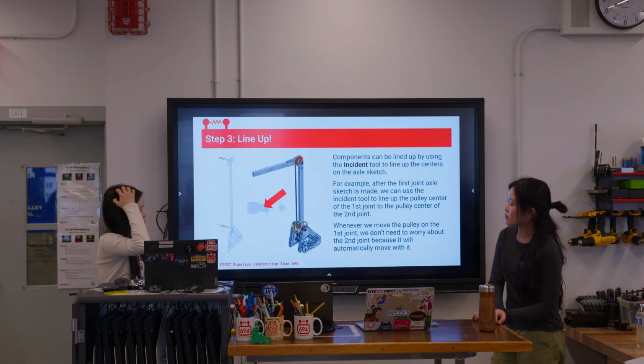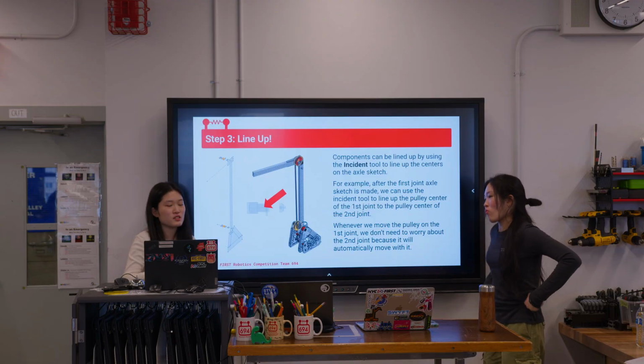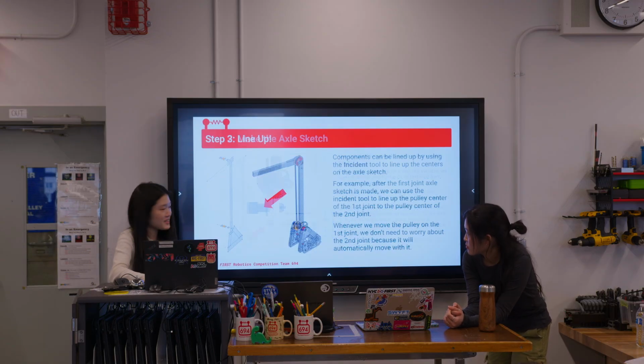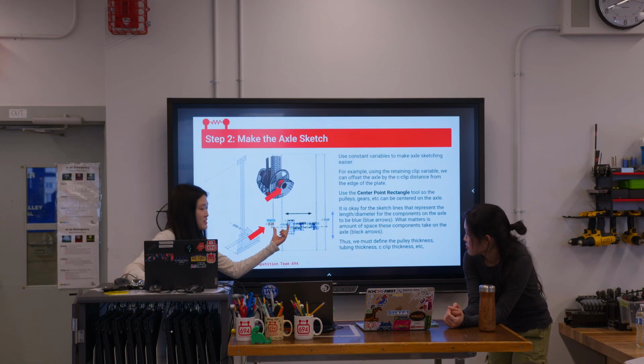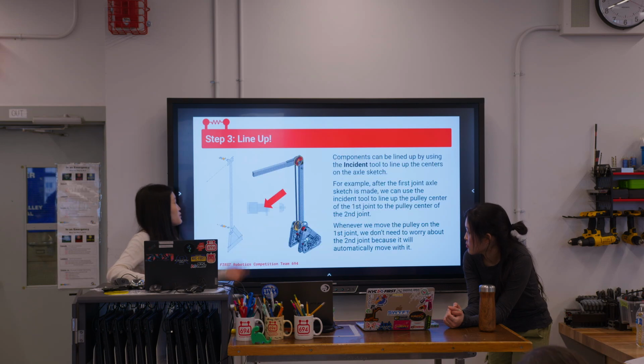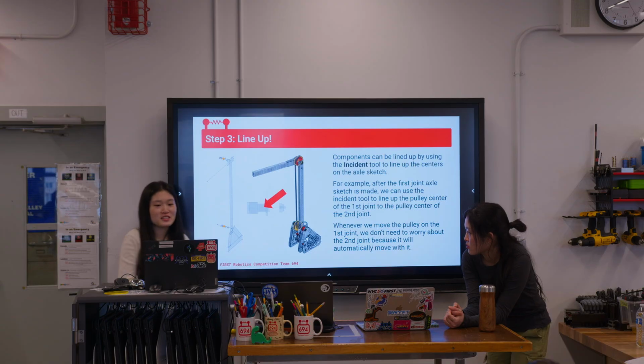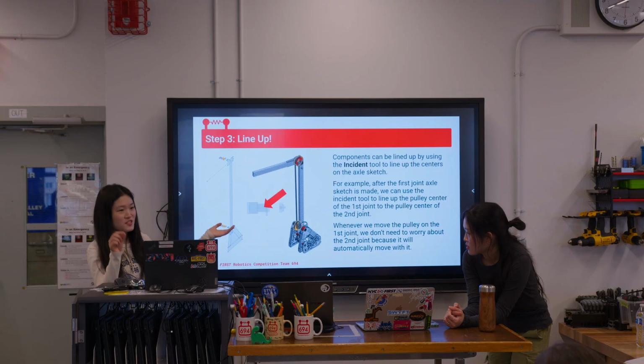Another thing that's really good, and this goes for all these mecha and robot sketches, is that it's really parametric. If I realize that I want to drag this a little to the side for some reason, then I don't even have to worry about this because this will automatically update on the sketch, on Parts 2, and even on the assembly. It'll just shift together. That's really nice. You can control everything with just one single sketch, drag it, and then everything moves.